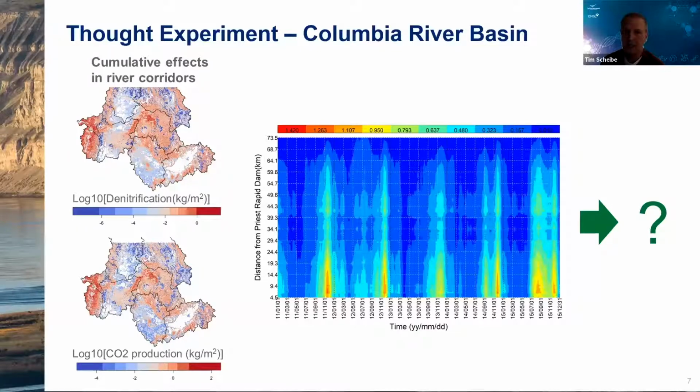That river stage variation leads to changes in inundation along the riverbank, as well as changes in exchange fluxes between the river and the groundwater. You also see an interesting feature over here in 2015, which was a low flow or a drought year. And we see that those hydropeaking features are actually exaggerated and even become bimodal during that drought year. So we can begin to see some of the effects of drought or of different hydrologic regimes on how the biogeochemistry of our hyporheic zone can function.